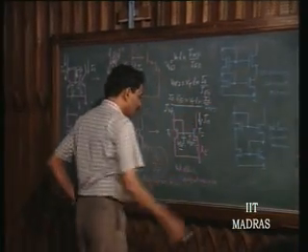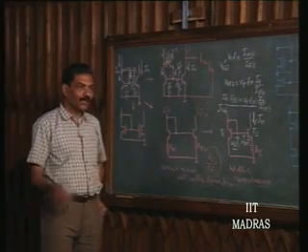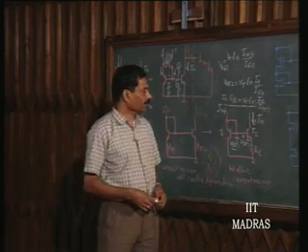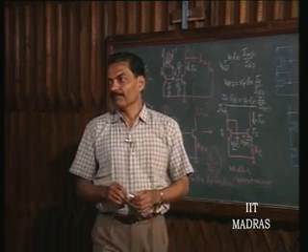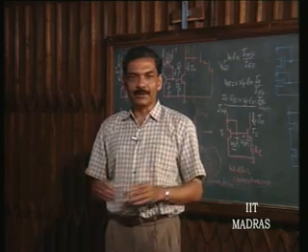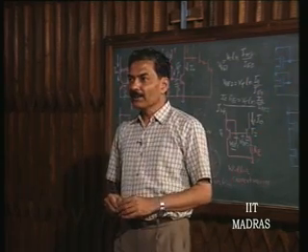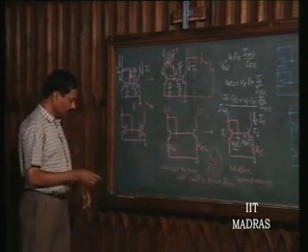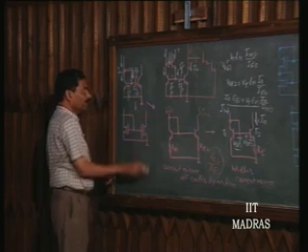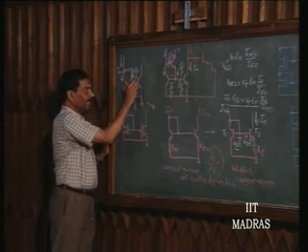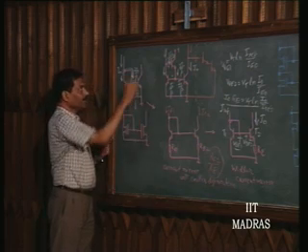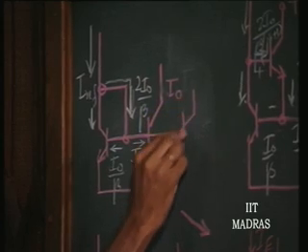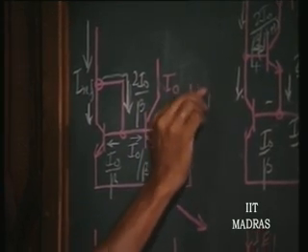This is again commonly used in all situations where I would like to generate a low valued current from a large valued current as the reference. But sir, instead of going for a resistance, we can scale the transistor sizes. Yeah, we are coming to that. We will come into that when we discuss further about translinear principle. Let us see, as he points out, a situation here, whereas I connect one transistor like this, the current is going to be I naught. Suppose I connect another transistor like this, current will be again I naught.